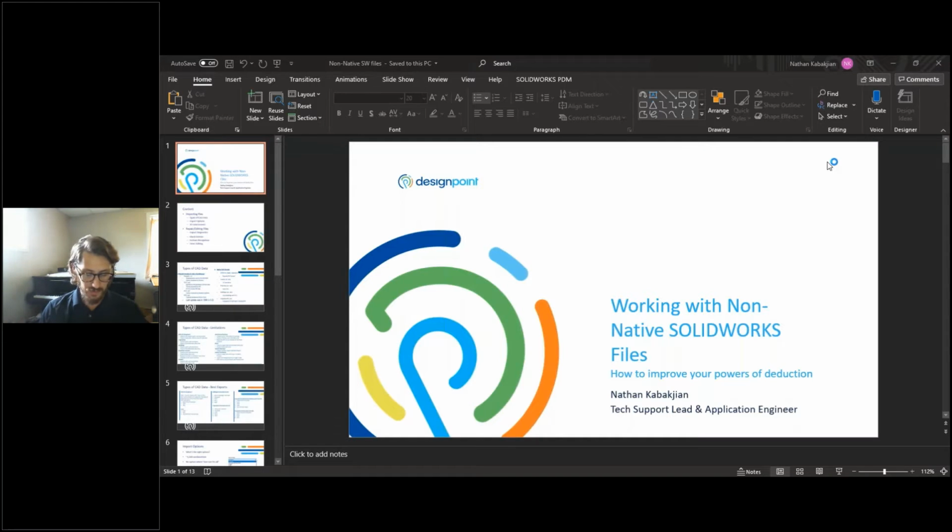The other bit of it is that if you are seeking CAD data from a vendor, it's best to know what types of file extensions you can ask for or prefer from them. And if they're available to give them to you, this hierarchy should help to provide you with a best case scenario for opening your files. One thing worth noting, Parasolid is the preferred method.